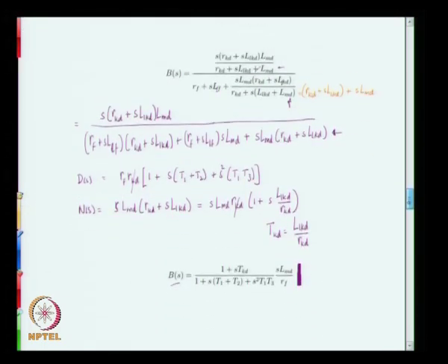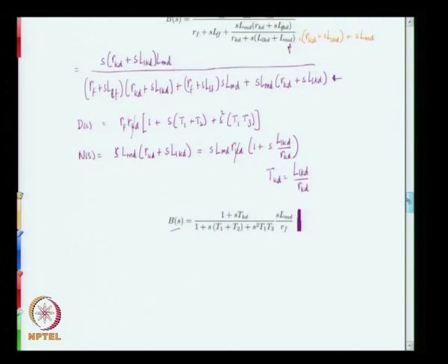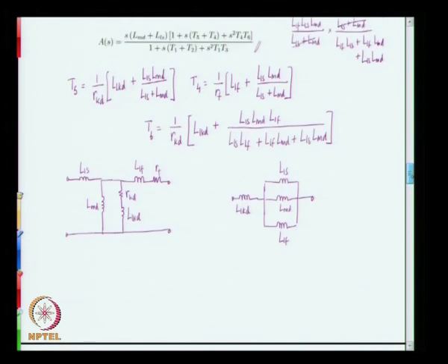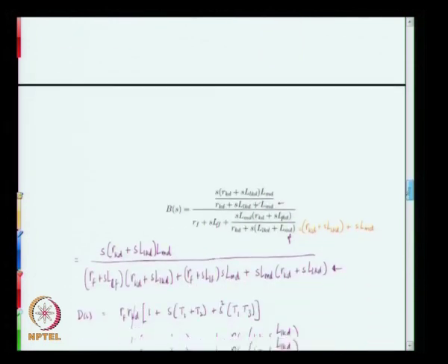For this case, this is just LKD by RKD, which is the damper part, and the denominator is the same as what we have seen. Note again that the denominator terms can be thought of as being open circuited, and the numerator then comes out as being where the armature terminals can be considered to be short circuited. So that is an interesting observation that we make.